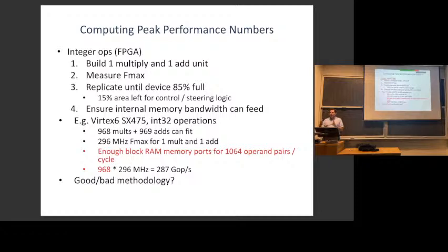They're basically assuming the data is on chip. For the processor, the L1 cache has to provide the data. For the GPU, they ask, can the register files, which are very large on a GPU, provide the data? And it can. In a GPU, it would be kind of crazy to build more integer units than the register file could feed. They do the same check for a DSP.